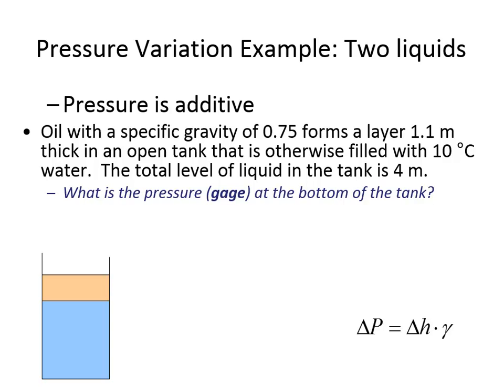Here's the hydrostatic equation. What would be the problem, do you think, if I said, here's location 1, here's location 2, let's just apply the hydrostatic equation in a single step? What would be the flaw with that approach? There is a flaw. What do you think? It's 2 different liquids.